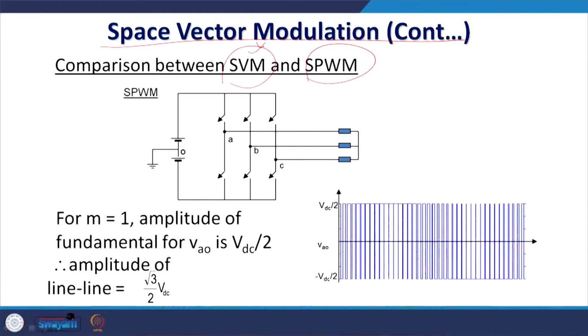SVM, but with the arrival of the digital age and fast processors, it takes the gain over the accuracy, like exactly generating the particular THD that you require, and it is attuned to vector control. So, for this reason this space vector modulation is gaining much attention. And so, what are the other advantages?